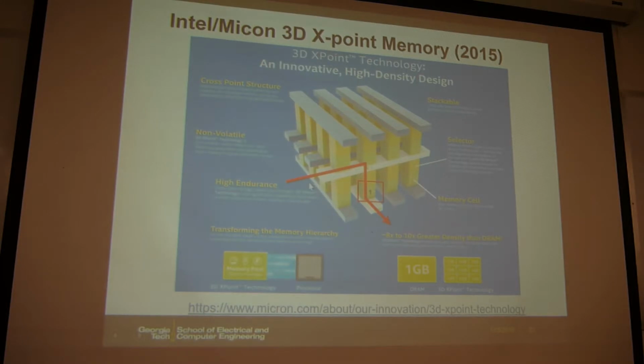So here this middle line is a shared bit line. So you have the 2 layers. So 1 layer here, 1 layer here. So each layer is a cross-point array. But the middle layer is a shared bit line.